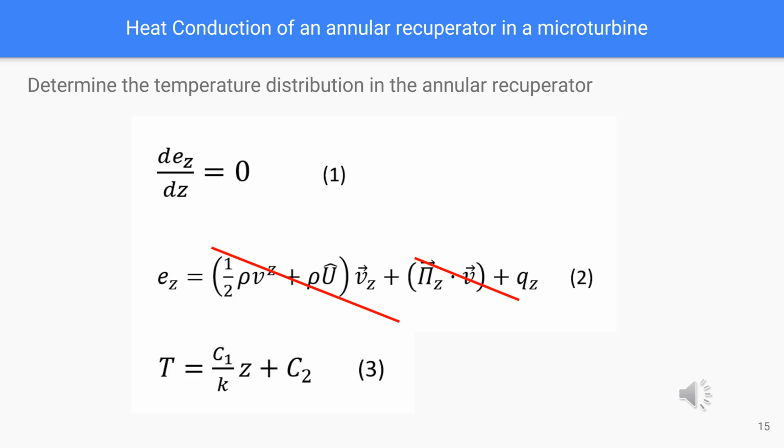Then once you write out and simplify your energy balance equation, you should get equation 1. That's when you write out the combined energy flux equation and do some more simplification. For instance, the first two terms in equation 2 cancel because there is no bulk fluid velocity within the control volume. This means that the only energy transfer in this problem is by Fourier's law of conduction.